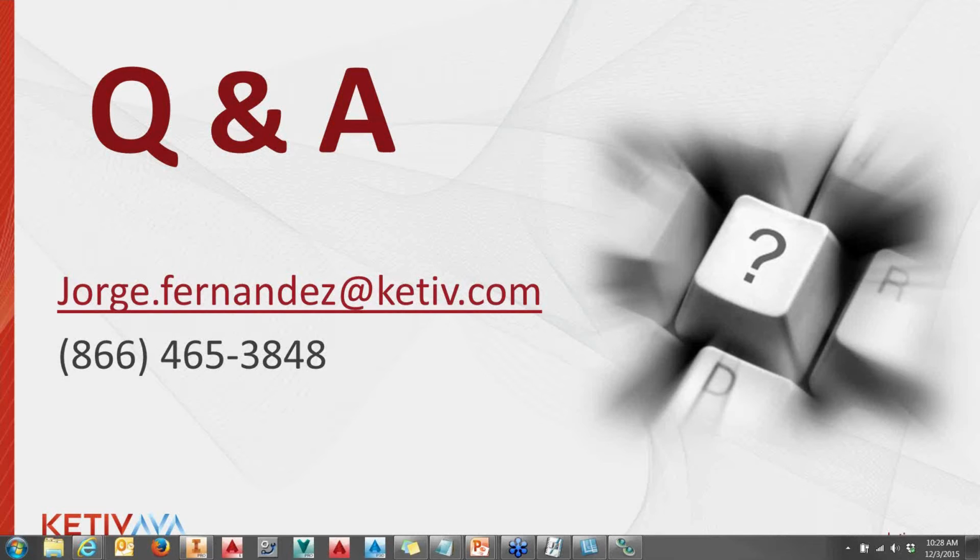And then we have a question here: how well does Inventor handle pressure vessel stress analysis? That one I might have to get a little more information on, actually. Hey, Jorge, can I hop in? It's Dave Graves here from Autodesk. Pressure vessels are a little bit challenging. It can handle somewhat of a pressure vessel, but it's going to assume a constant pressure unless you split surfaces.